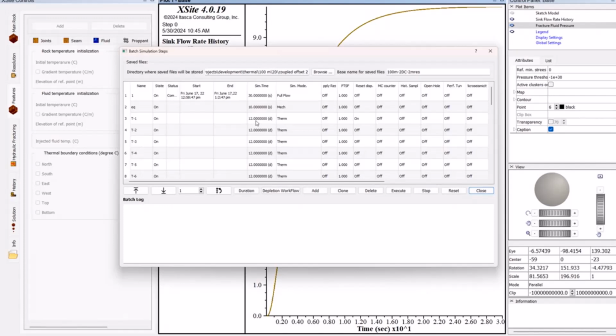And then in the following step, after we reach the mechanical equilibrium, we carry out the simulation of the injection of a cold fluid. We carry out these simulations using this optimized THM scheme, where we run the model simulating heat advection, and then periodically execute the conduction model to see the effect of the exchange of heat between the rock and the fluid on cooling of the rock.